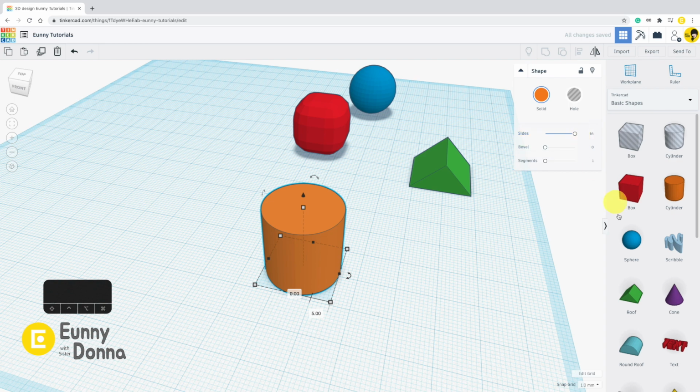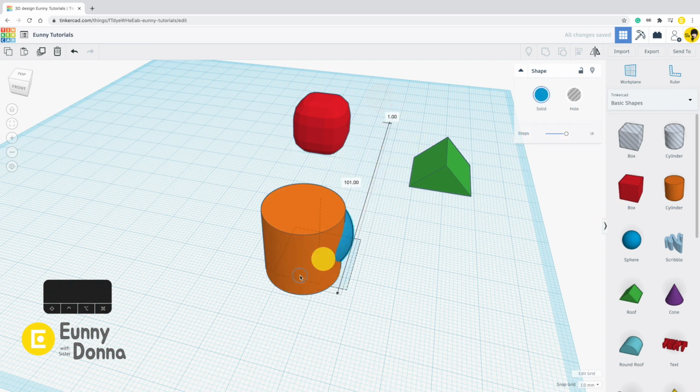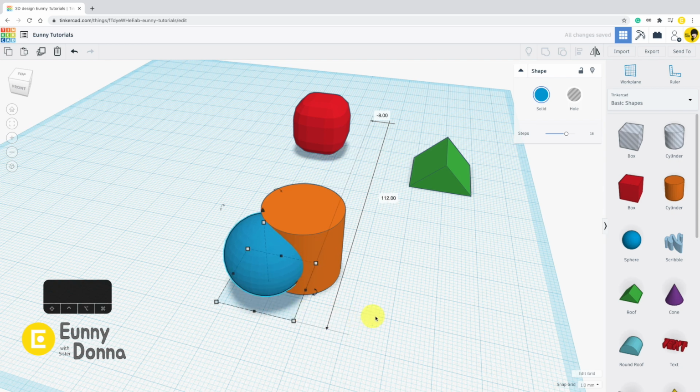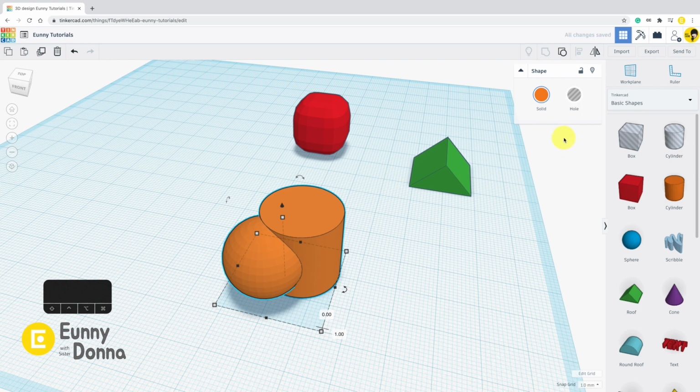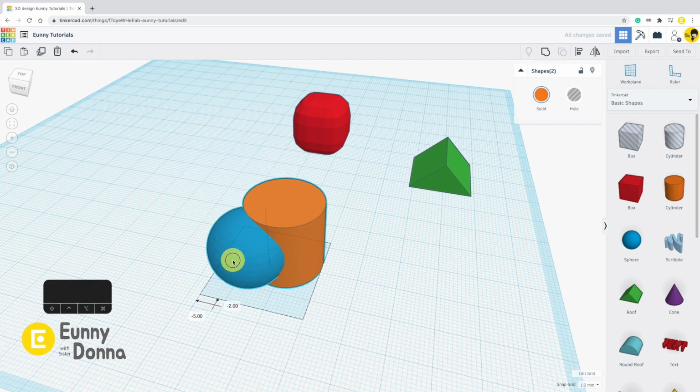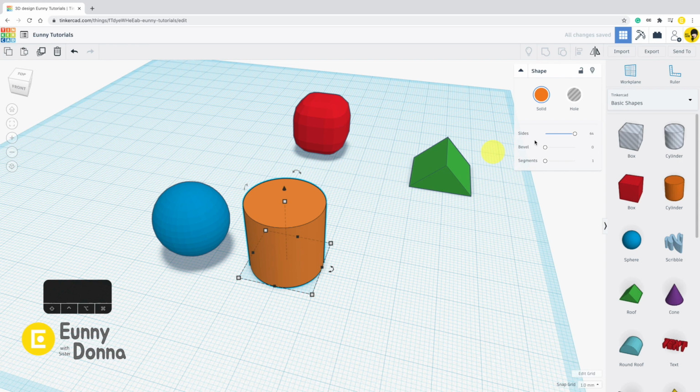Here is one tip for you. While you are working on 3D modeling, you might attach shapes to others or group them. The thing is that once you group the shape to others, you cannot modify the properties of each shape anymore. It is important to customize the essential properties from the beginning. Especially if you are going to print round objects like a cylinder, you need to set size as max value.